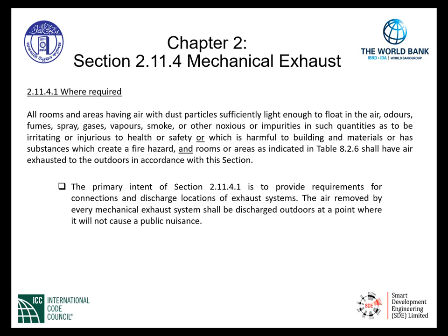Now, the primary intent of this section, Section 2.11.4.1, is to provide requirements for connections and discharge locations of exhaust systems. The air removed by every mechanical exhaust system shall be discharged outdoors at a point where it will not cause a public nuisance.